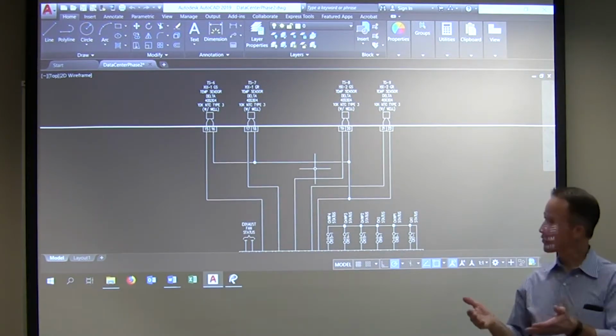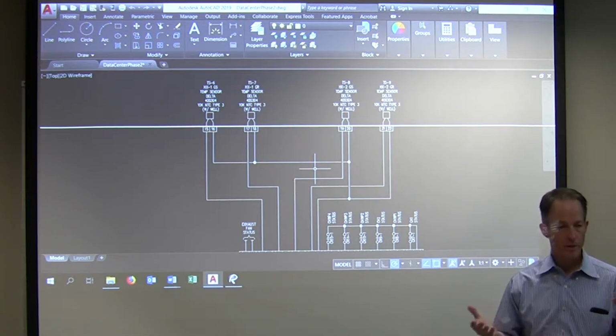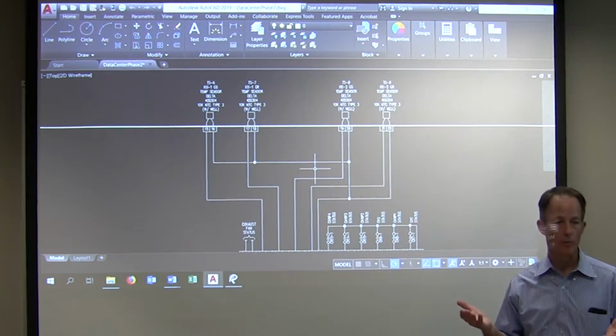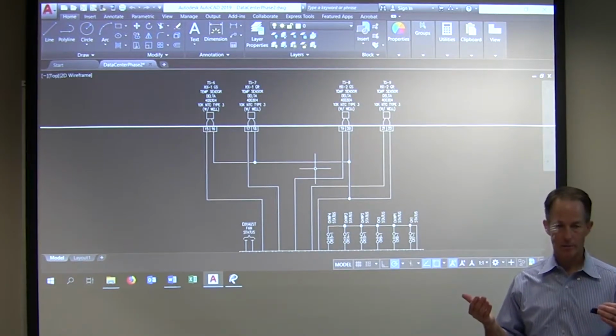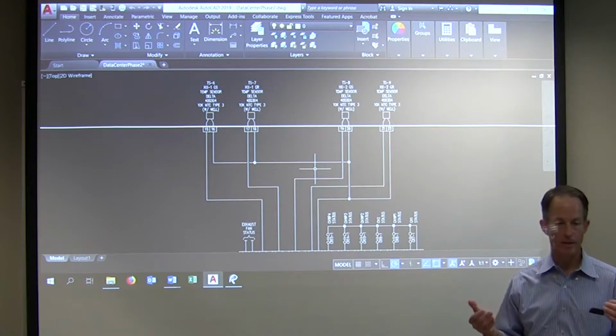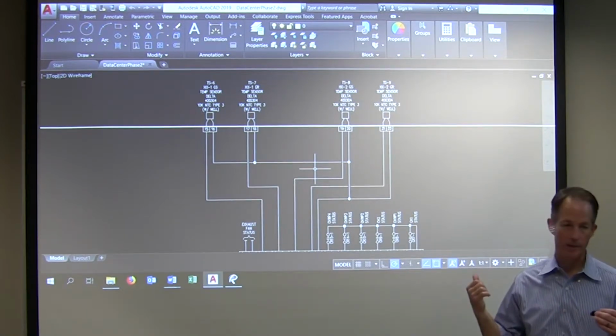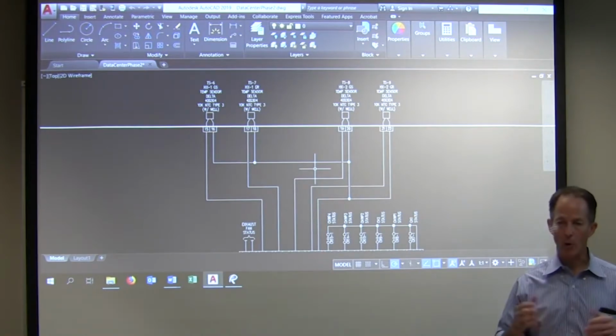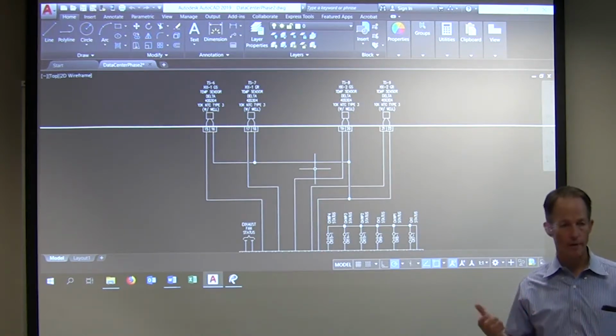So 5 or 6 ohms compared to 10,000, is that very much? It's pretty minimal, right? We're talking tenths or hundredths of a percent that it introduces error-wise. So if we don't care about a half a degree, is that wire length going to make any difference? No, it's insignificant. We've got more error in the sensor itself than the wire introduces.